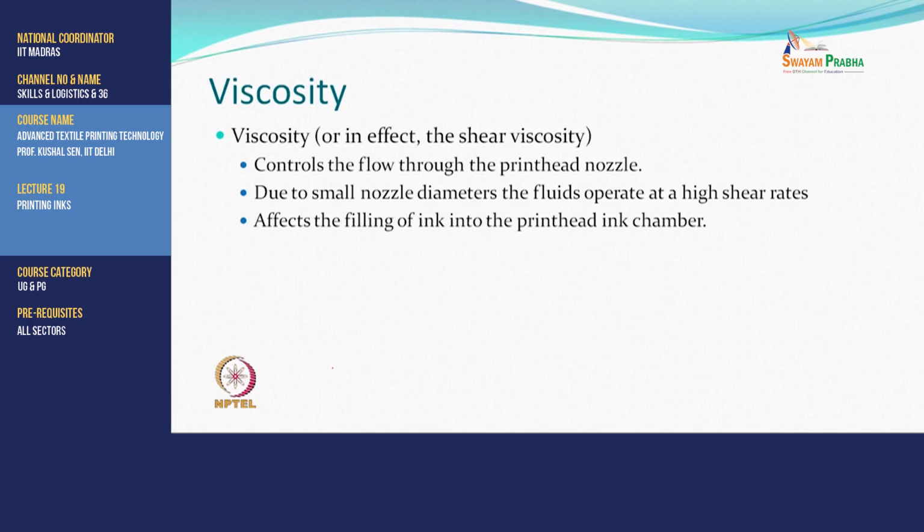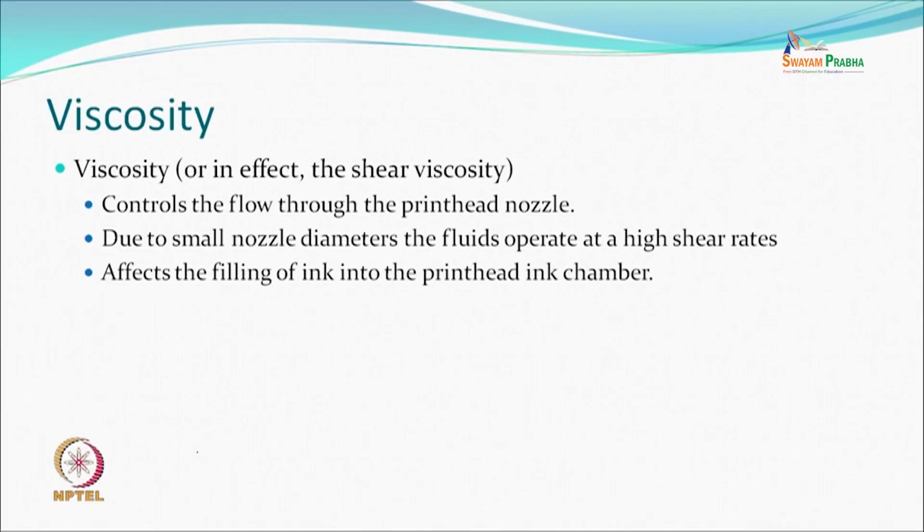So when it is coming out, it should be at a high shear rate, but when it is stationary, its behavior is different. So the behavior of the ink, whether it is going to be shear thinning or shear thickening, this is what will be important for us to learn.